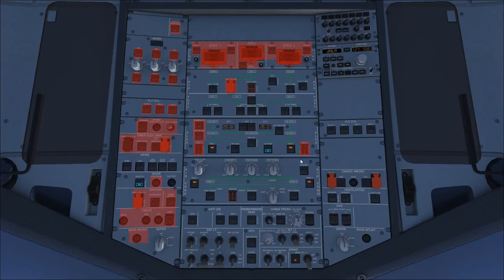The next panel is the air conditioning panel. So this allows you to control the air conditioning within the aircraft. So you've got your two PAC master switches on the left and right. PAC is an acronym for Pneumatic Air Cycle Kit. And it's these systems which control the environment within the plane. They control the pressure and the temperature of the air within the plane. So you can enable these systems by toggling them on and off.